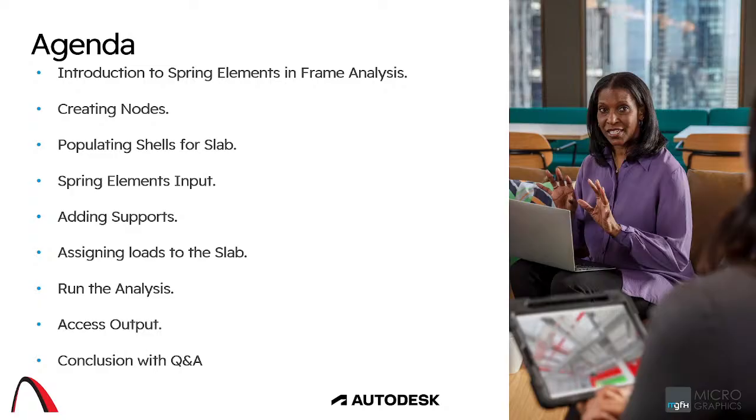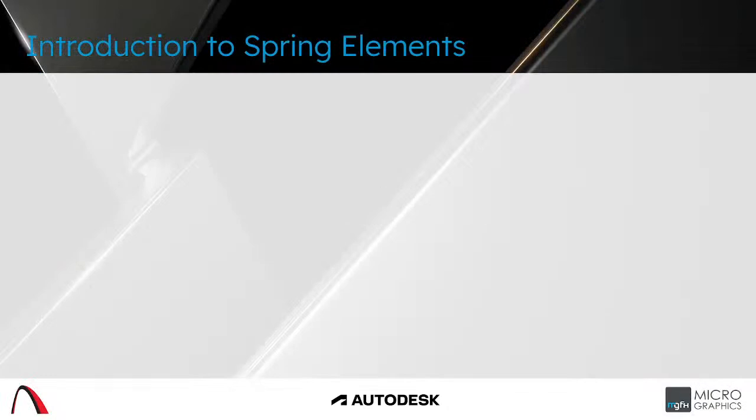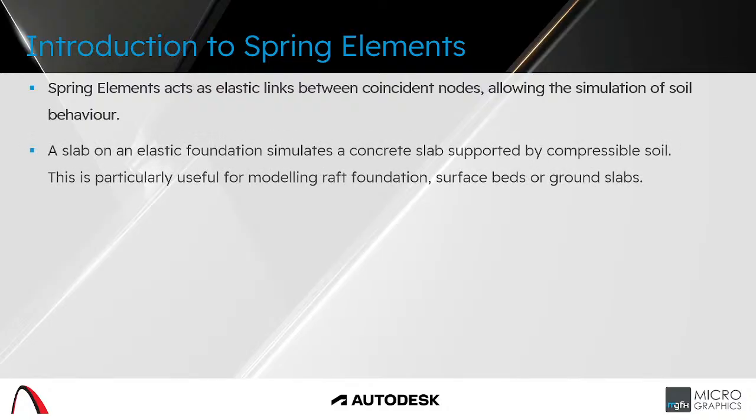So without wasting any time, let me start with the introduction to spring elements. So the first thing is spring elements act as elastic links between coincident nodes, allowing the simulation of soil behavior. And then the other thing that we will be doing is a slab on an elastic foundation. It simulates a concrete slab supported by a compressible soil.